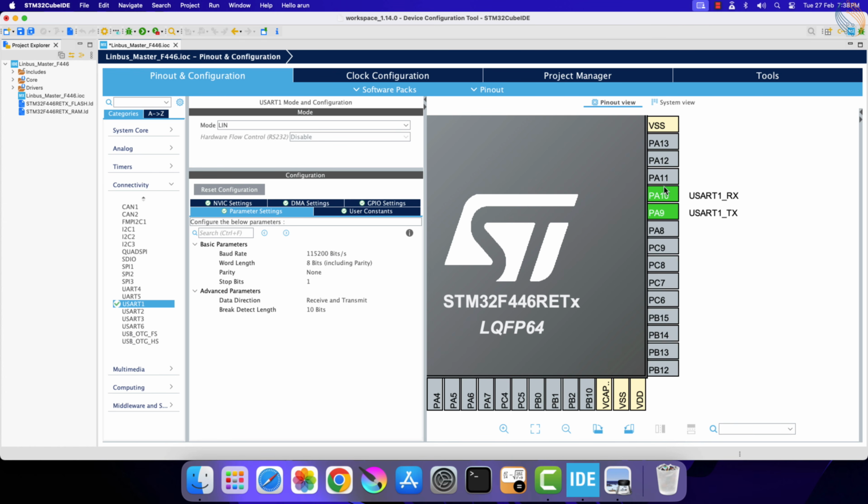The LIN bus used in cars generally uses 12-volt signals, hence the use of a transceiver is necessary. I will connect a LIN transceiver in the next tutorial, but today we will just focus on the TX pin. The data sent by the MCU will be via this pin, so we will monitor this pin on the analyzer.